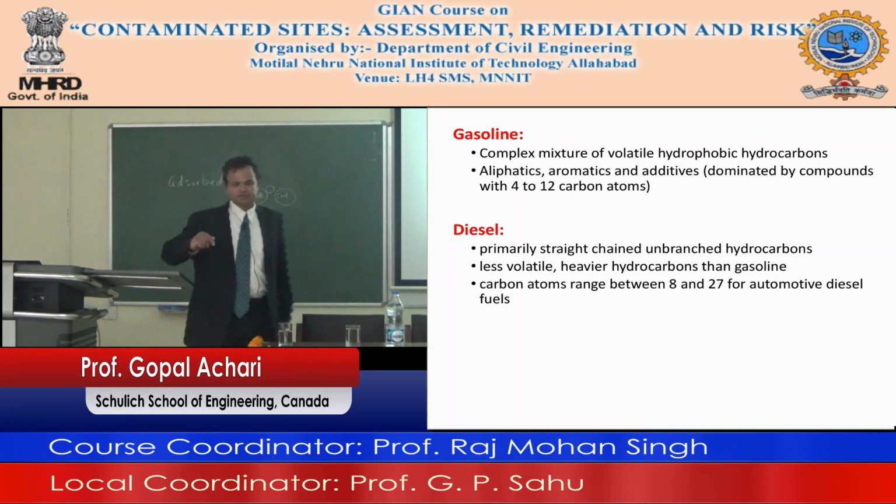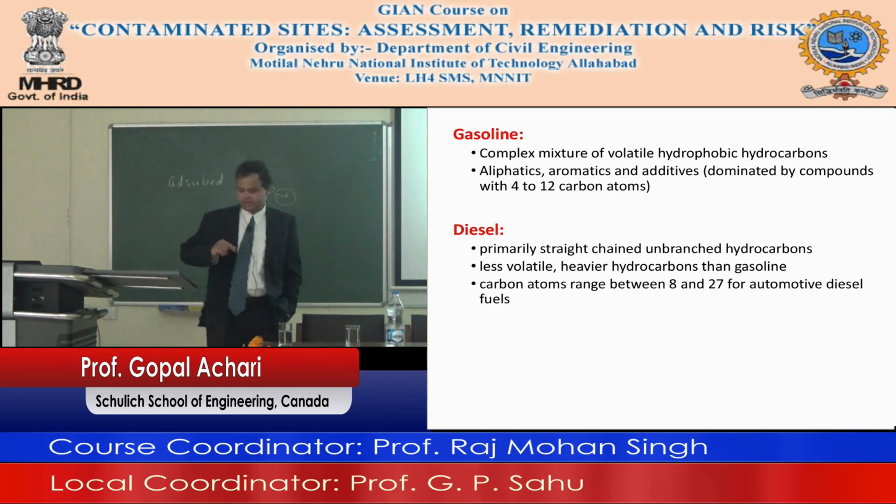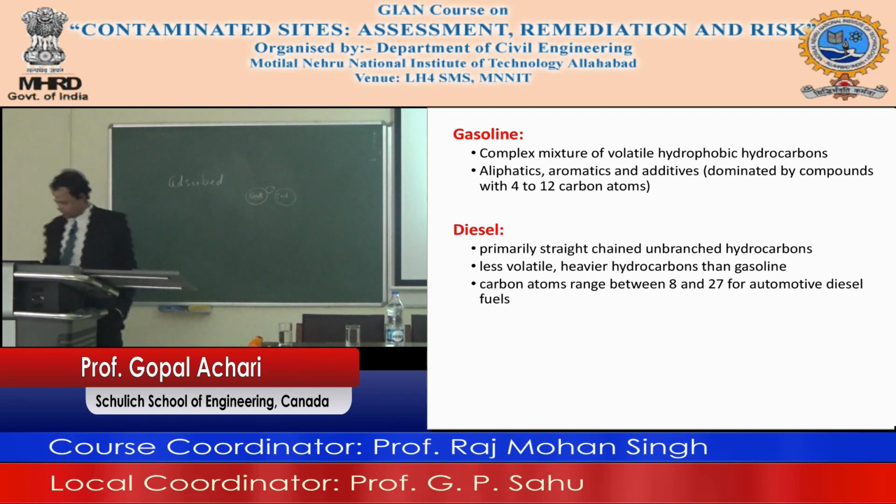I come from a colder climate, and in places where it's really cold, you need the diesel to have an even higher fraction of heavier material for it to work. Diesel fuels for railroads and bunker fuels have even longer chains. Then they add additives to give cold start at minus 20 degrees Celsius. So diesel fuels have different varieties depending on where you are.